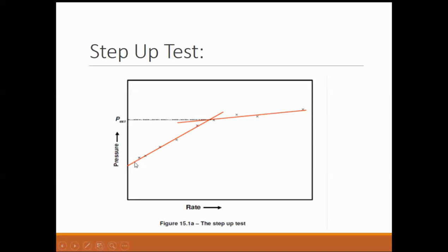You should be sure whether the production decrease has happened because of decreasing tubing size, or has it happened naturally, or do you have evidence of skin developed across your perforations? Then only you should go for hydraulic fracturing. There are some cases in which, before hydraulic fracturing, you can use some chemicals or acid jobs, oxidization, which can give you equal results. In those cases, you will not opt for hydraulic fracturing as the optimum solution.